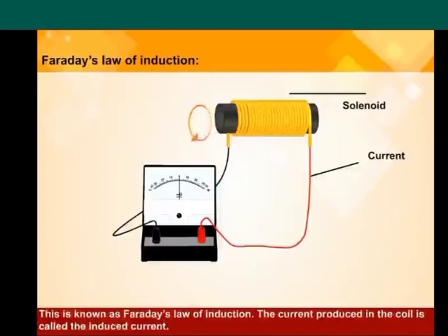According to Fleming's right-hand rule, electric current is produced in the branches AB and CD in the direction A goes to B and C goes to D. Thus, the current flows in the direction A goes to B, B goes to C, C goes to D, as shown by arrows in the figure. In the external circuit, the current flows from B2 to B1 through the galvanometer. If instead of one loop coil, a coil consisting of several turns is used, the current of magnitude several times